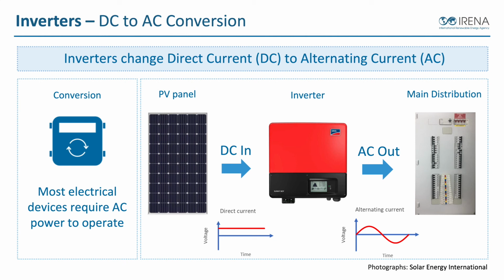So if we buy the right inverter type, we can have this inverter automatically synchronize to a utility grid, matching up its voltage, its frequency, its waveforms, and able to push that solar power into an AC electrical system and match whatever type of electrical system we have. And so that's where we're going to use an inverter: to convert energy and then synchronize it if we're connecting to the utility grid.